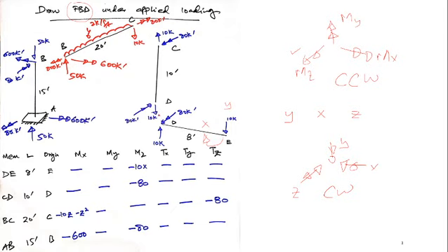Next I have to balance this joint D. This 10 kip is upwards, so I have to balance it with a downwards 10 kip. This 80 kip foot is counterclockwise, so I have applied an equal and opposite one in clockwise direction. Next, this 10 kip is balanced here, and you know this is clockwise, so I have balanced it with anti-clockwise 80 kip foot.